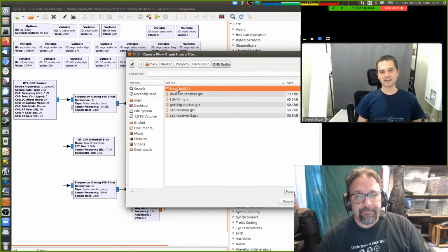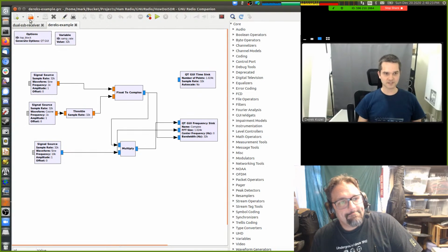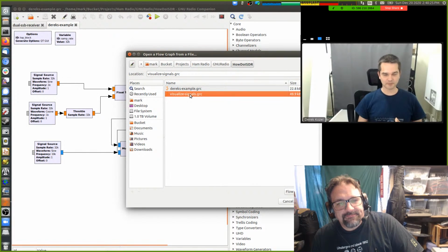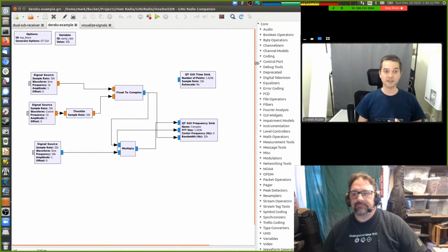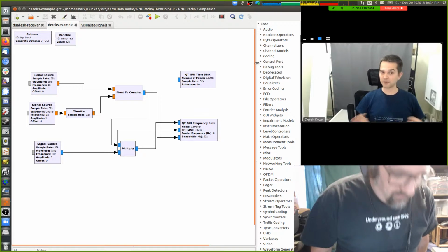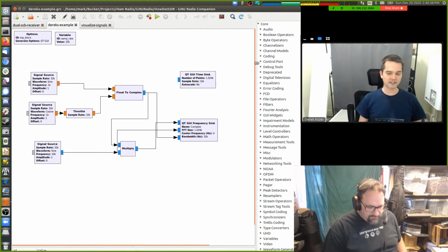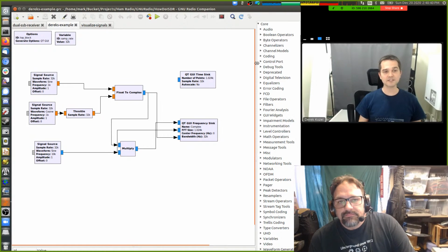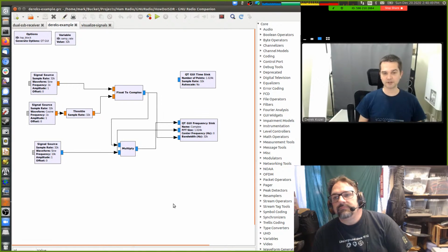Go ahead. I suppose one of the main things that I think was interesting is we worked our way through what a complex signal is, as a pair of sinusoids, and that the sum of the sinusoids at the same frequency gives you another sine wave. This is a property unique to sine waves, basically, that depending on the phase relationship of the sine and cosine, or the I and the Q components more accurately, you either get a positive frequency or a negative frequency.